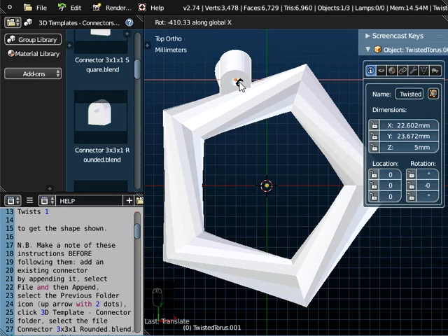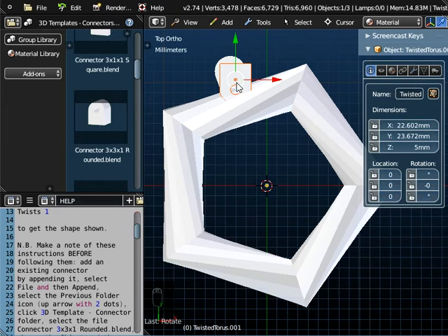And normally you want to rotate 90 degrees, 180 or 270. So the best thing is to type in 90 and see whether that works. Now as you can see, it has rotated about the x-axis, but it's rotated it in the wrong direction for us. So we want to actually now rotate it 180 degrees.